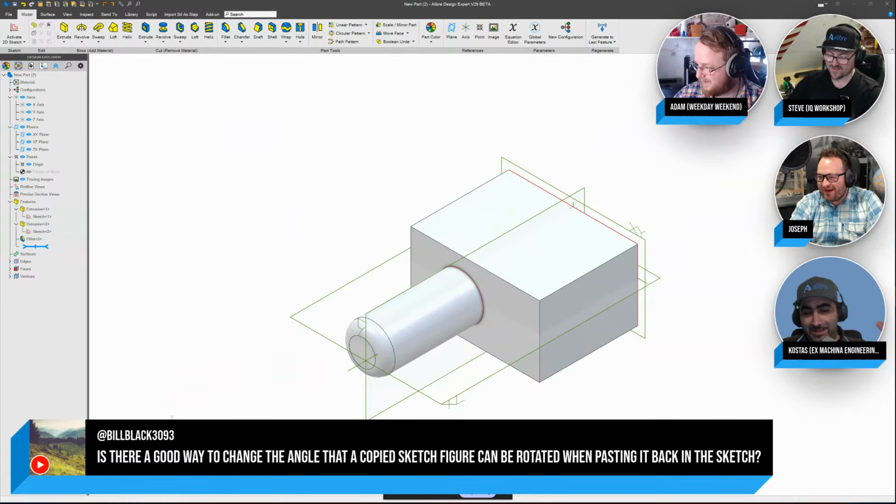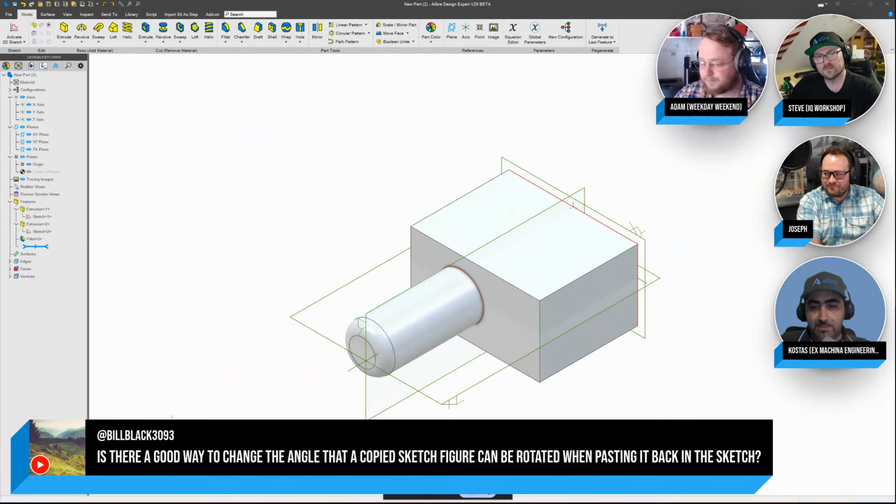What you need to know there, Bill, is that when you're using the paste stamper and you copy with a base point, then you can stamp what you copied, and you also stamp the constraints and dimensions. So if you have an angle dimension there, you can stamp it and then change those. For example, you're copying a square and picking up the dimensions as well, you stamp it, and then you can change those dimensions and make a different square. That's a really powerful use of the paste stamper, and you can do all sorts of stuff with that.